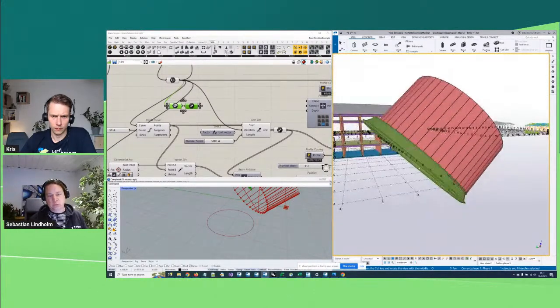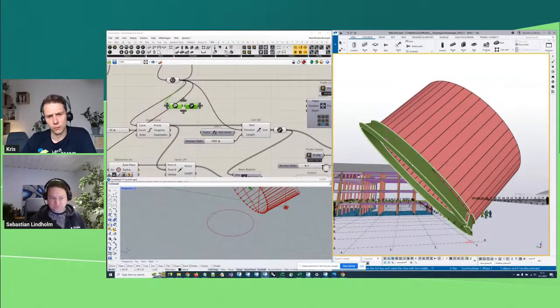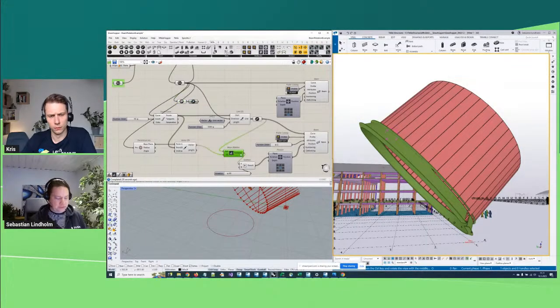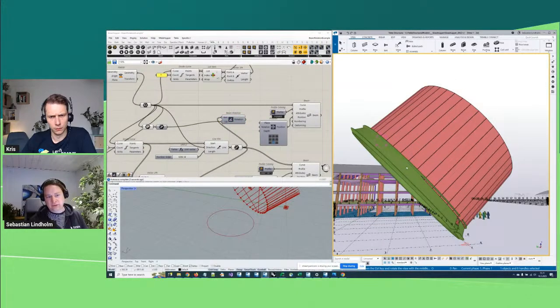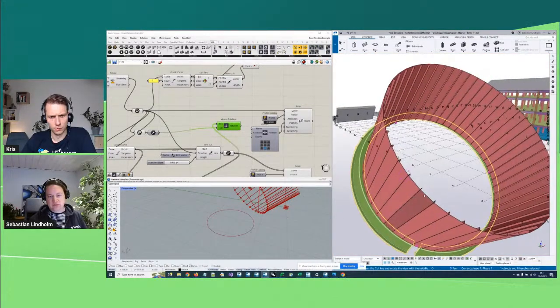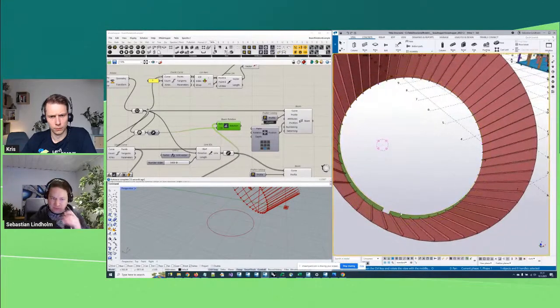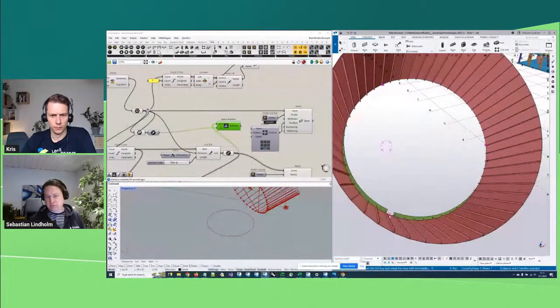And what we also notice here is that when we tilted this circular beam, it actually starts to warp because it also needs to be rotated. And we can use the beam rotation component for that as well. So here the up direction will be that same direction that we just talked about, straight out of the circle. But the next question is, what's the beam axis for a circular beam? This is one thing that's perhaps not very intuitive, but this circular beam is defined using just 3 points, and the chamfer type is arc, so it creates a circle. But in Tekla, for any beam or polybeam, the axis is actually from the first control point to the second one.